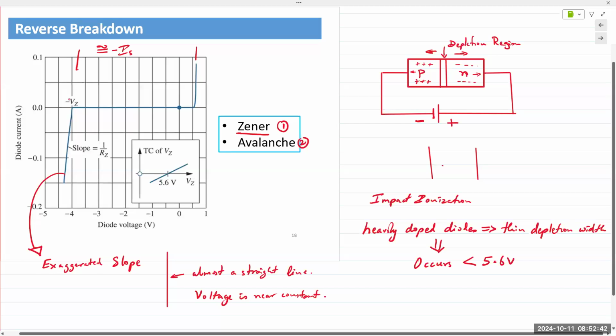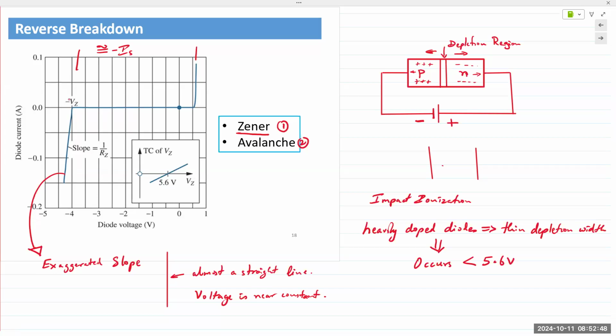And so depending on the requirement, engineers can calculate the amount of doping that is required and create Zener diodes to work in the reverse bias for, like, say, 2 volts, 3 volts, 4 volts, 5 volts, going up to like hundreds and thousands of volts. Okay. So you could connect a diode, stick it in the wall in reverse bias, 110 volts, it will still work fine.